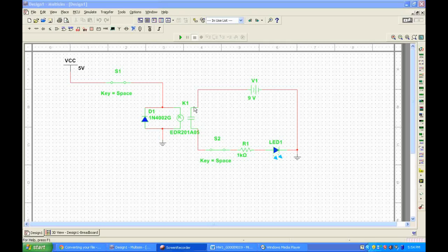The relay that I would use would be a latching relay. The reason I would use a latching relay is because when you have the motion detector activated, it sends one pulse to the relay. A normal type of relay would require continuous current to it in order to keep the secondary circuit active. And so with a latching relay, once it got one pulse from the PIR sensor, that relay would latch closed, allowing this circuit on the right here to continue operating.